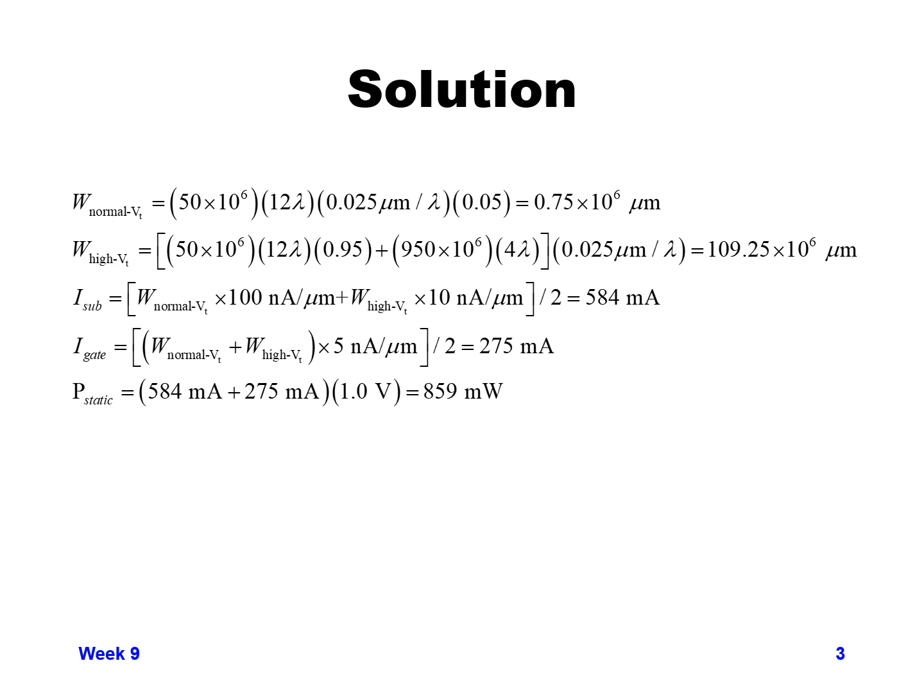So we take total transistor width and the total leakage determined there, and divide by 2 to get our total leakage, because again only half the transistors are leaking. And that gives us 584 milliamps worth of leakage.